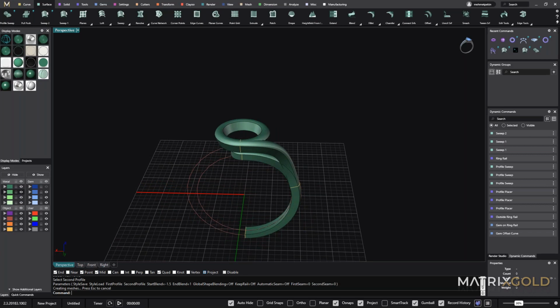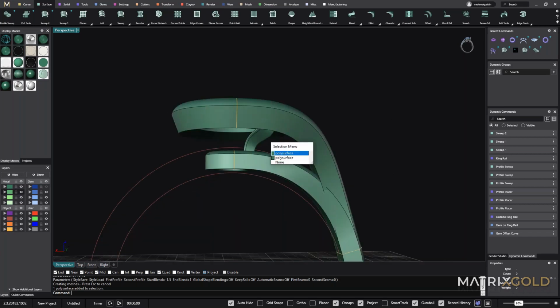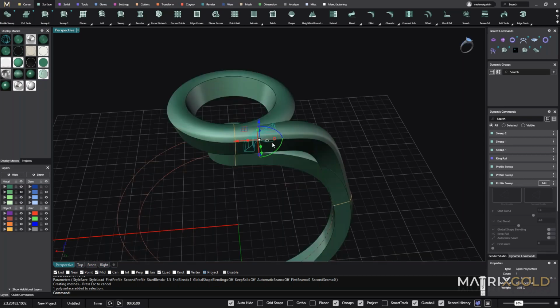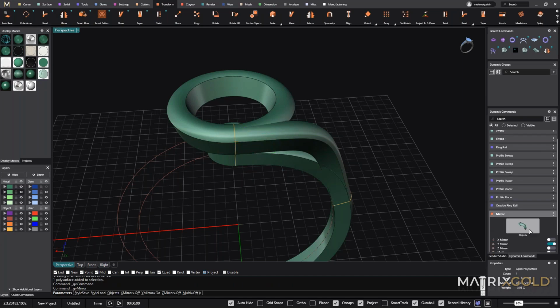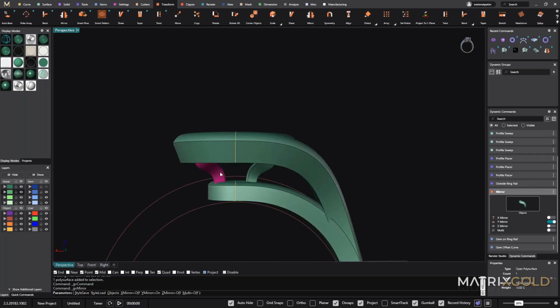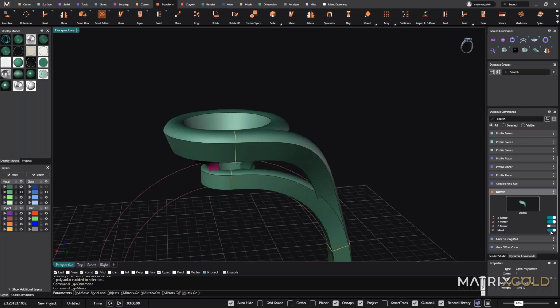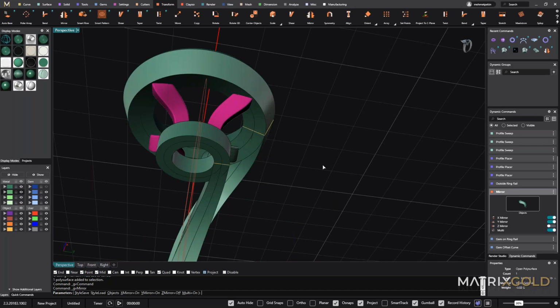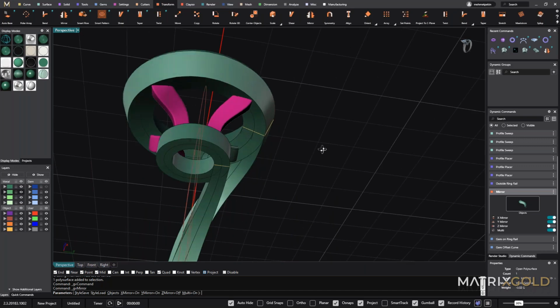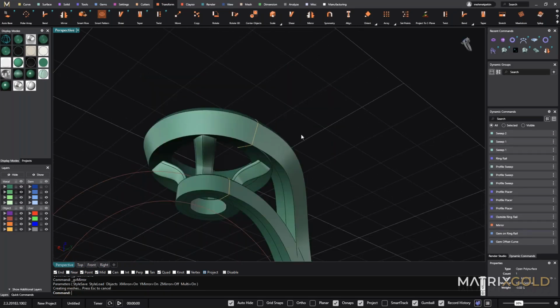First of all, I want this one, this polysurface for quad symmetry. I'm going to select the transform menu with parametric mirror, when I select this part, and you can also mirror to the left side, but when you select the X mirror and you can select multi option here, you can copy to the quad sides. When I select enter, now you have 4 of them here.